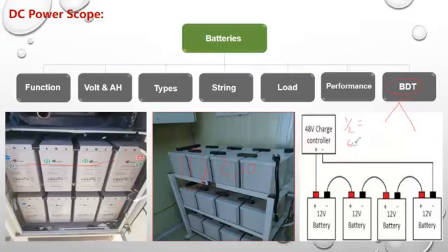After 60 minutes, I see the battery measurements as well, and after 120 minutes it is the same, in intervals of half an hour each. I start to see if the batteries discharge properly and logically, or if there is a battery that is not discharging well.